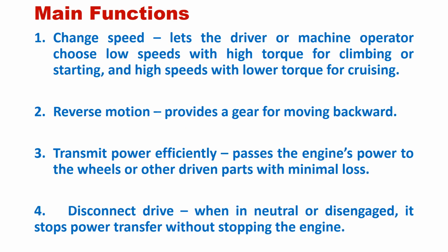Then, the main functions of a gearbox: change of speed, one. Second, reverse motion. Third, transmit power efficiently. Fourth is disconnect the drive. Change of speed lets the driver or machine operator choose low speed with high torque or high speed with low torque. Whatever you want, it will be changed.